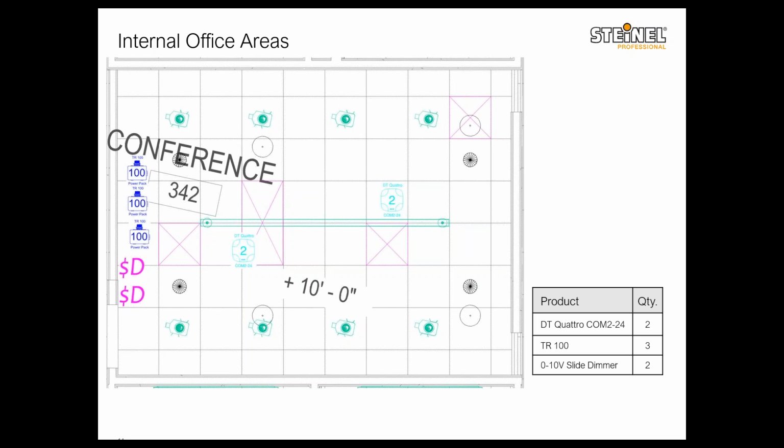Again, I can't say for sure, but unless the windows are from floor to ceiling, we wouldn't need daylight responsive control for this, because probably only those 4 fixtures at the top of the slide would be in your daylighting zone, and I'm guessing they are not more than 20 watts each, so 4 of them is about 80 watts, which doesn't qualify for this daylight responsive control anyway. So that's why I dedicated the whole segment to that application.